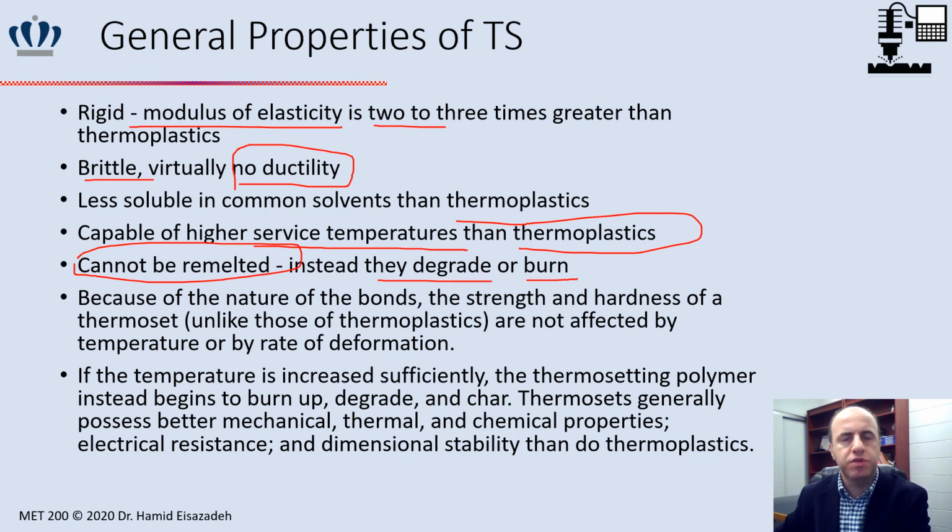For the thermoset material, you need some sort of energy, for example, heat. Some thermosets, such as epoxy or polyester, can be cured at room temperature because the heat produced by the reaction is sufficient to cure the plastic. And the reaction is called exothermic. Exothermic.